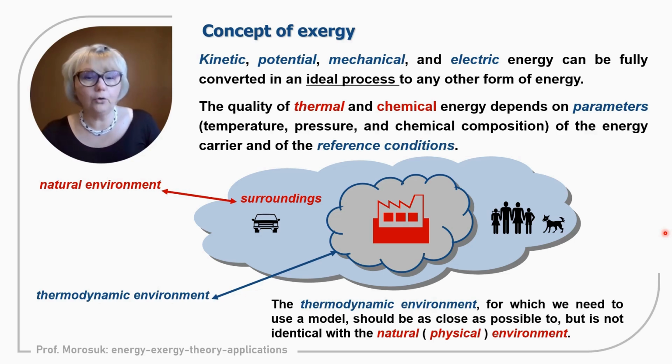Remember the concept of entropy, where we already used the thermodynamic environment. The thermodynamic environment is just a model, something hypothetical which does not exist in real life. It should be as close as possible to the natural environment, but nevertheless, it is not the same. And for the thermodynamic environment we should always describe all the assumptions that we use: temperature, pressure, and chemical composition we need to describe.